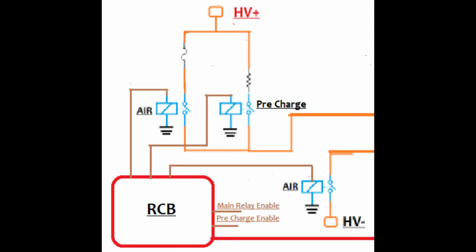But there's also one last component that we haven't talked about yet, and it's that little red line that you see going to the RCB, which is another signal called the shutdown circuit. I'd like to explain the shutdown circuit through explaining the HVD, as these two are correlated to one another, in how the shutdown circuit flows through the car. So let's go through that first and clear up another main goal of this video, which is how the shutdown circuit works.